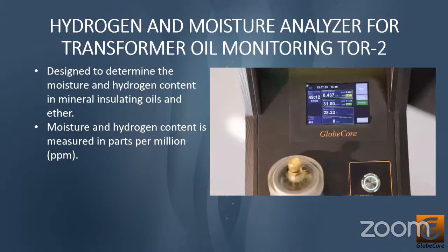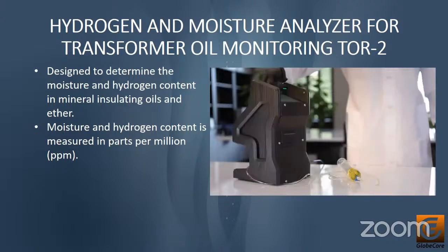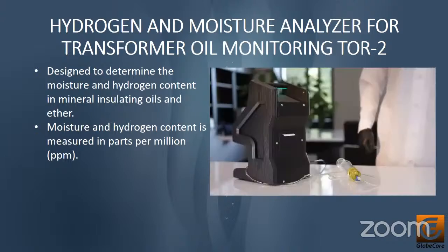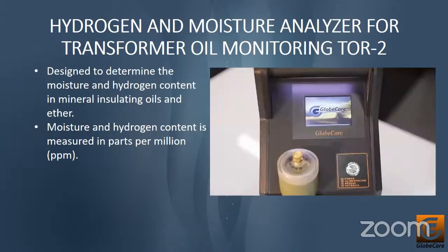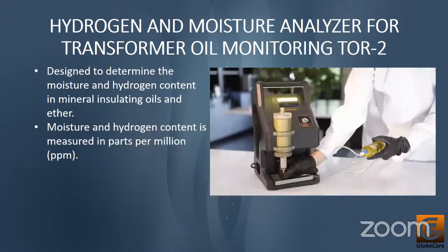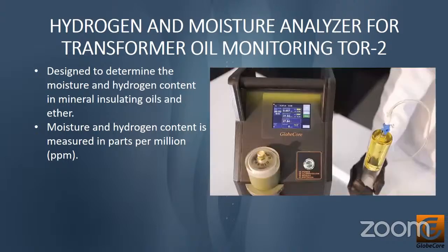Hydrogen can contribute to the degradation of the insulation properties of transformer oil and insulation materials, which can affect the efficiency and safety of the transformer. Knowing the amount of hydrogen in oil is a good indicator for determining the state of thermovacuum processes, the gassing processes, or regeneration processes.